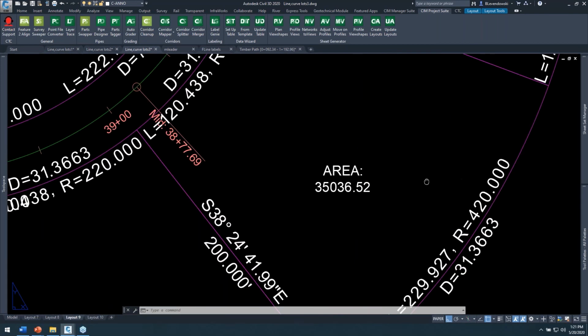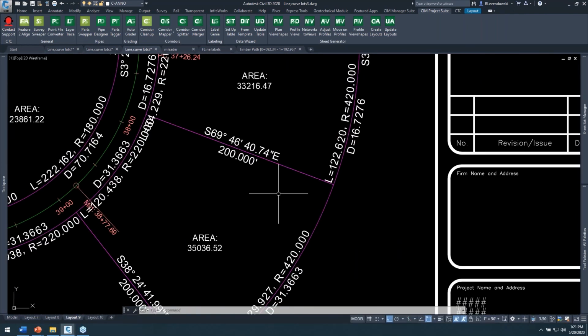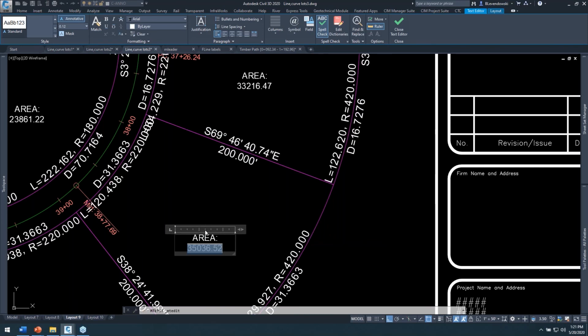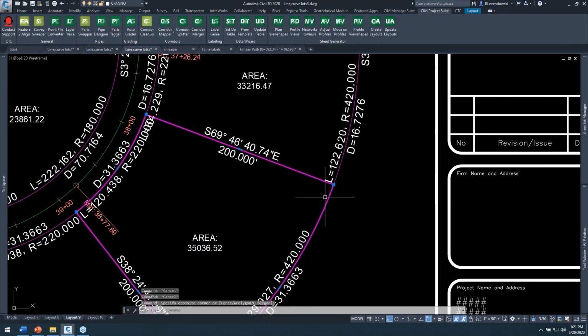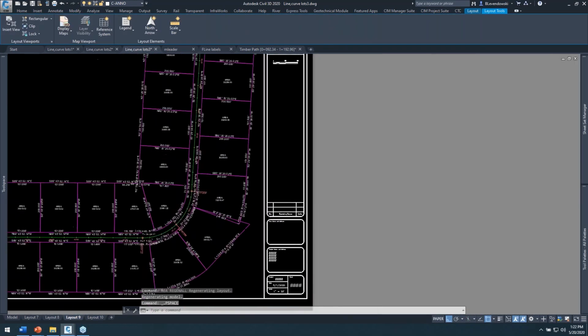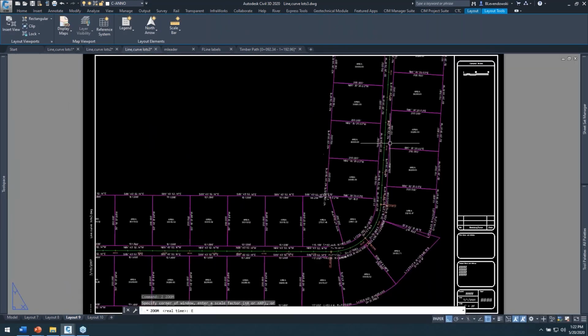And like I said, it's an AutoCAD field. So an AutoCAD field is dynamic. This isn't functionality. I mean, this is native stuff here. You look in here, this is an AutoCAD field. It's being linked to an object, to the area. Okay, we're just automating the insertion of that field. But if you're not familiar with fields, it means when the source object changes, a region and the area or the value itself will update. Okay. Those are handy, but they're really clumsy to build because you got to build one at a time.